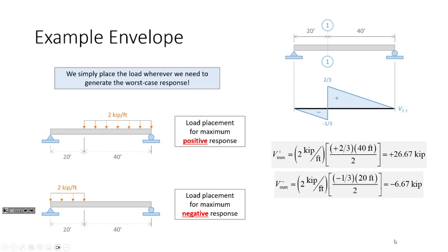And so what we do in bridge engineering is I picked a point 20 feet from the left support. Well, that'll work for that point, but how many points do I need to pick? And this is where I said common practice is to do this analysis at 10th points along the bridge. So, and we'll talk about that a little more on Monday.